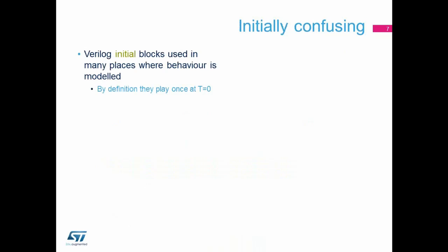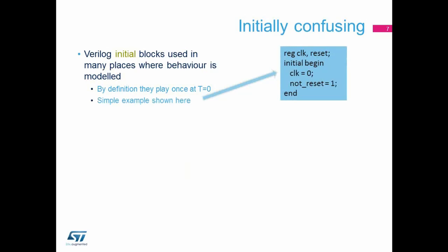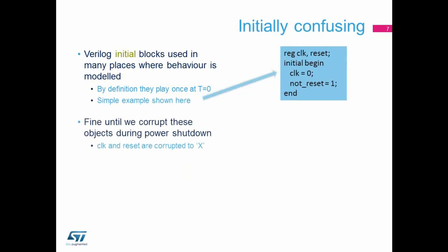Here's some stuff about initial blocks in Verilog. We've got a lot of places in our code where we've got initial blocks in models. By definition, they play once at time 0. There's a very simple example there.